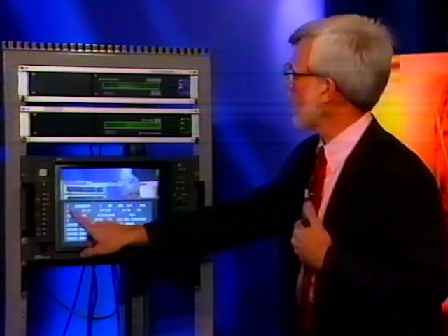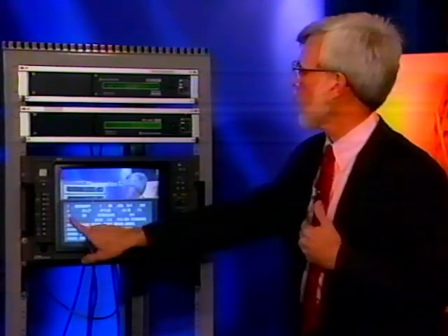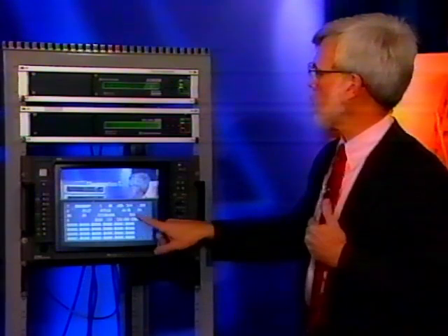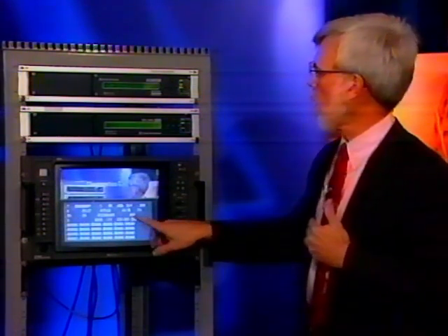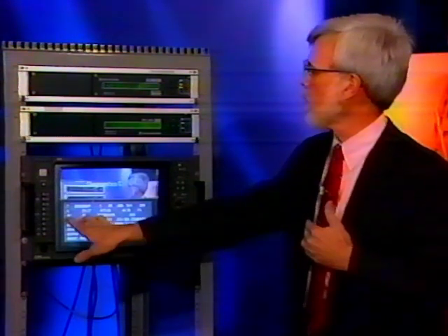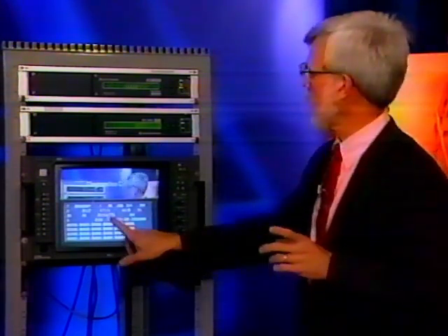The other one that's of importance is on line 3, 1, 2, 3. This is a series of numbers that actually are the worst signal that the unit has received, the best signal, and then 2 numbers that actually go into an equation that give us an idea of how stable the signal is. Once again, if you're having trouble with your signal, we may ask you to give us that information. And then that all-important one, the one that everyone's interested in, is the Eb/N0, the EBNO number, and that is in the next line. Right now, I'm showing a 7.8 to a 7.9 here.